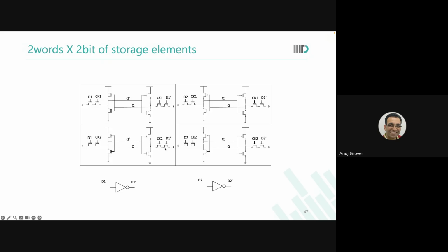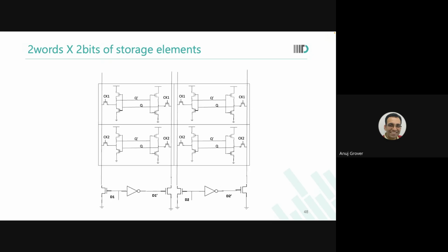So what is happening? Can we do still more sharing? Yes, let's try. So what we do is we make this D1 transistor also common. And what we get is a 6 transistor cell, which is repeated over and over again. But the 6 transistor cell cannot function independently because that D transistor we have pulled out. What is this particular NMOS down there? This particular NMOS becomes a part of the write driver.